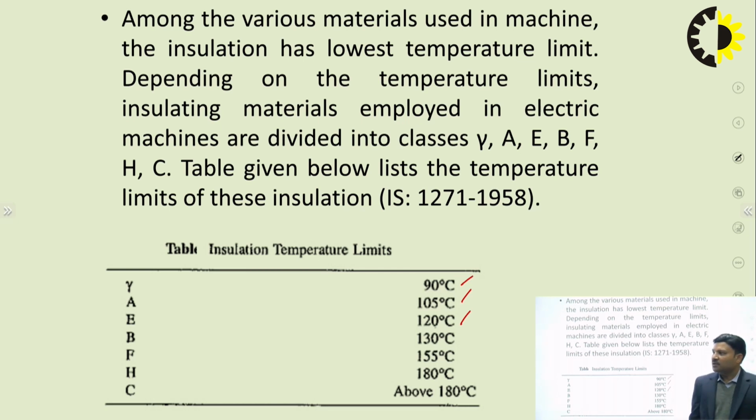Most of the faults in industries occur due to failure of the insulation. So one must understand the application, what the maximum temperature could be, and on that basis the insulation material for the winding should be selected, such that in the occurrence of any type of fault, the insulation material remains in its original state. It should not melt. In many applications, when there is some transient condition or fault, the insulation fails, and due to this there is a short circuit in the motor.